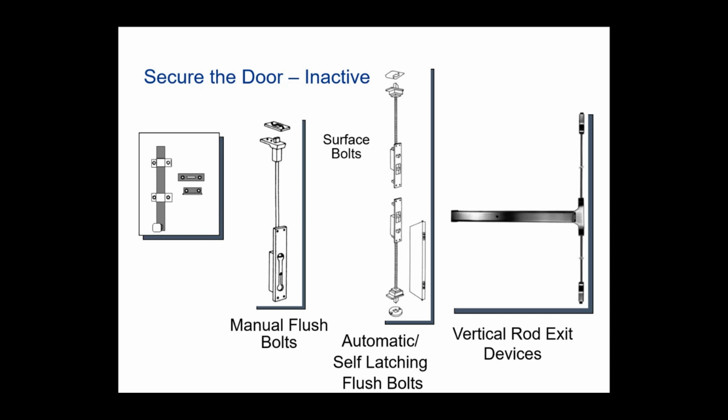You'll find this most commonly at pump rooms or maintenance rooms, and you can only put these in at non-rated inactive leaves of doors. If a customer or an owner wants to put this in after you have your certificate of occupancy and after the fire marshal has come through and approved the opening, the following year, whenever their building is inspected, they'll have to remove that device.